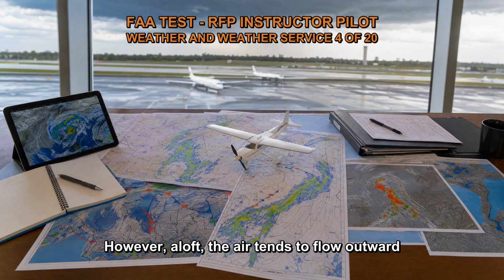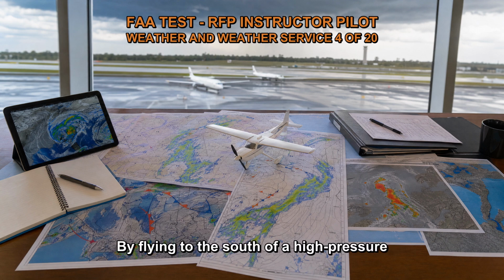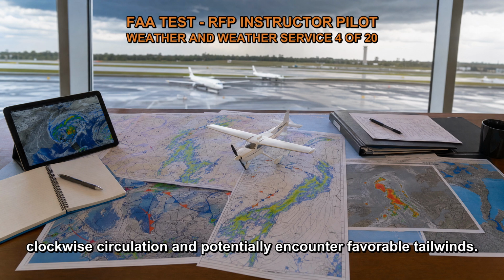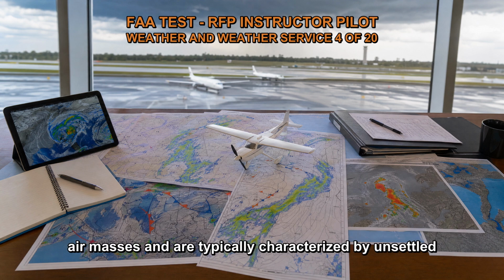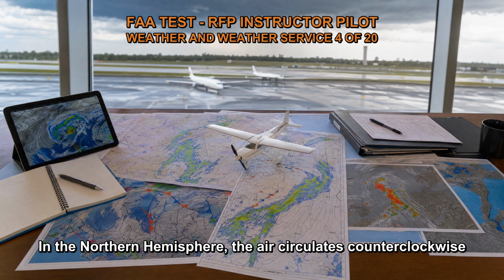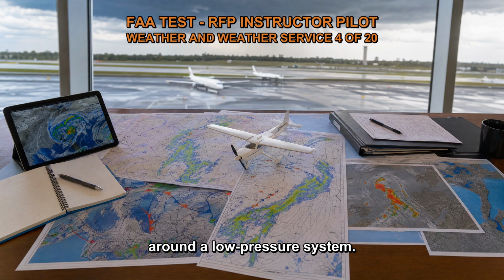However, aloft, the air tends to flow outward from the high-pressure system. By flying to the south of a high-pressure system, a pilot can take advantage of the clockwise circulation and potentially encounter favorable tailwinds. Low-pressure system. Low-pressure systems are associated with ascending air masses and are typically characterized by unsettled weather conditions. In the Northern Hemisphere, the air circulates counterclockwise around a low-pressure system.